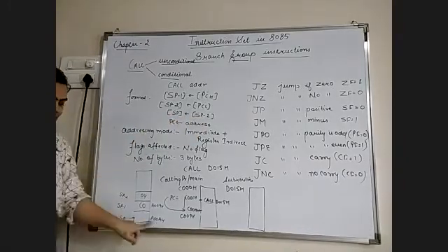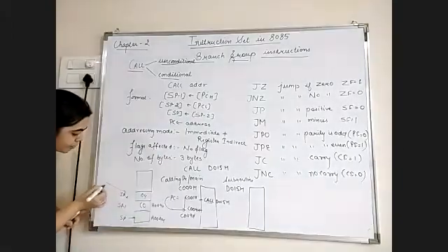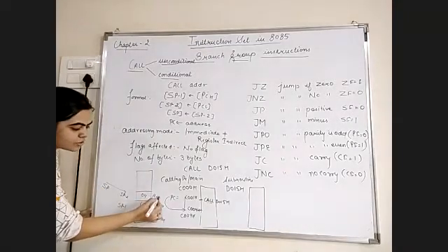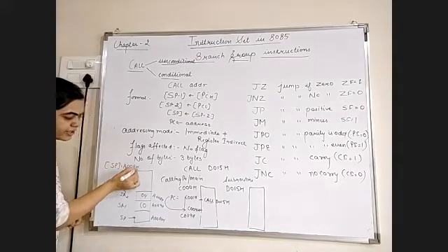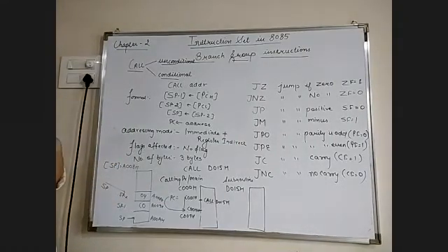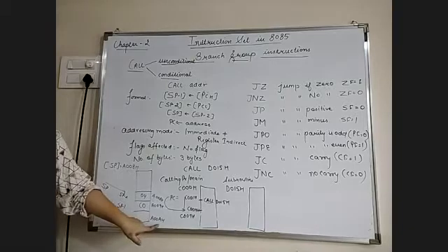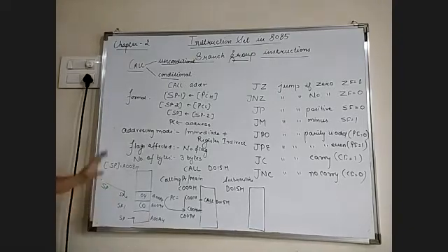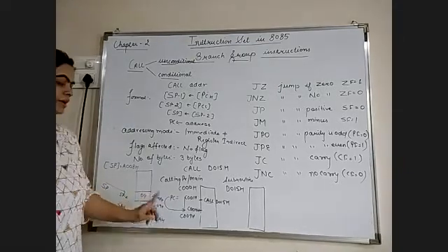So before execution, the stack pointer was A00AH. After execution, the stack pointer points to memory location A008H. So after execution, the stack pointer has the value A008H. That means this is the register indirect way, because the contents of the program counter are pushed into the memory location which is specified by the stack pointer. And the stack pointer specified which memory location? A00AH.